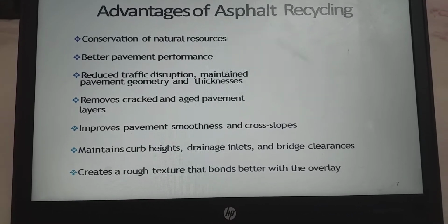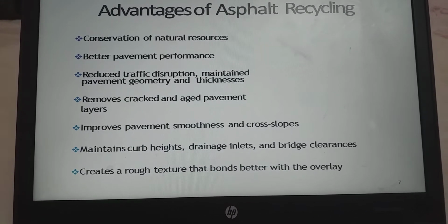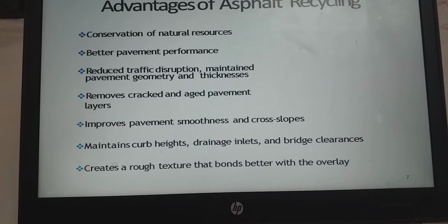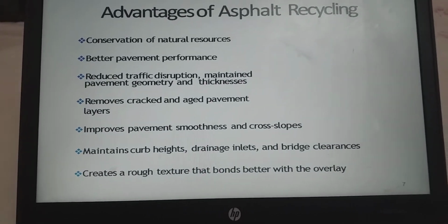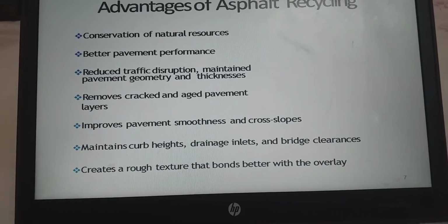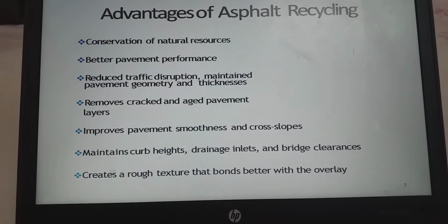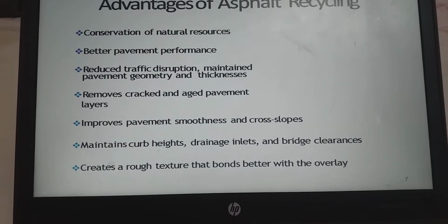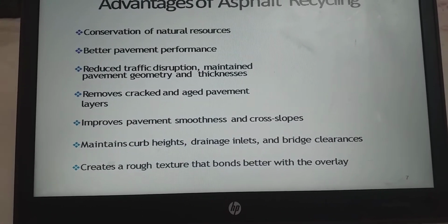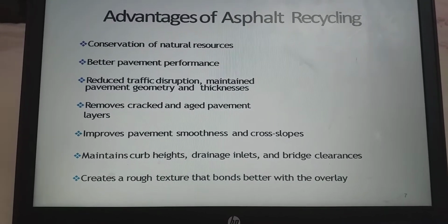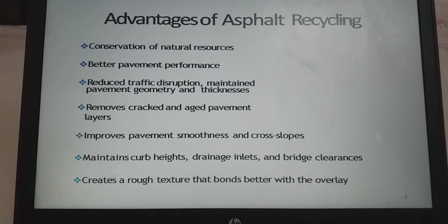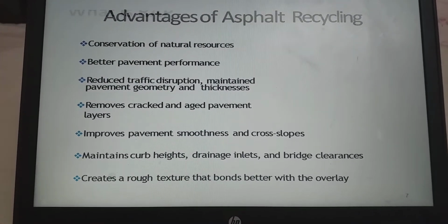Then we can remove cracked and aged pavement layer. We can improve pavement smoothness and cross slopes. Then we can maintain curb height, drainage inlet and bridge clearance. Then we can create a rough texture that bonds better with the overlay. So these are the advantages if we recycle the asphalt.